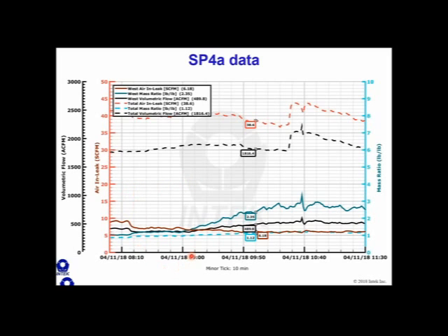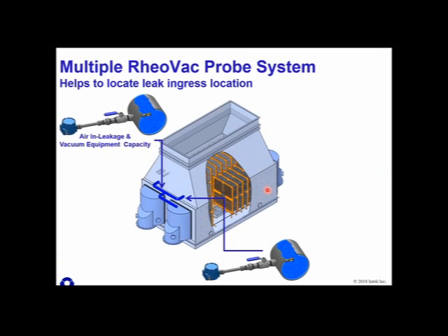So with a two-revac approach, you can narrow your search for leaks. It looks like the leakage into the condenser is closer to the east path tube bundle. So let's go back here. We might have a leak coming in the wall here, or maybe in the transition hood here, closer to this east path bundle. That air would go in, enter this bundle, and get evacuated out this pipe, and it would not travel all the way around the condenser and come out this pipe, okay? So there's air in-leakage closer to this bundle and not this bundle.